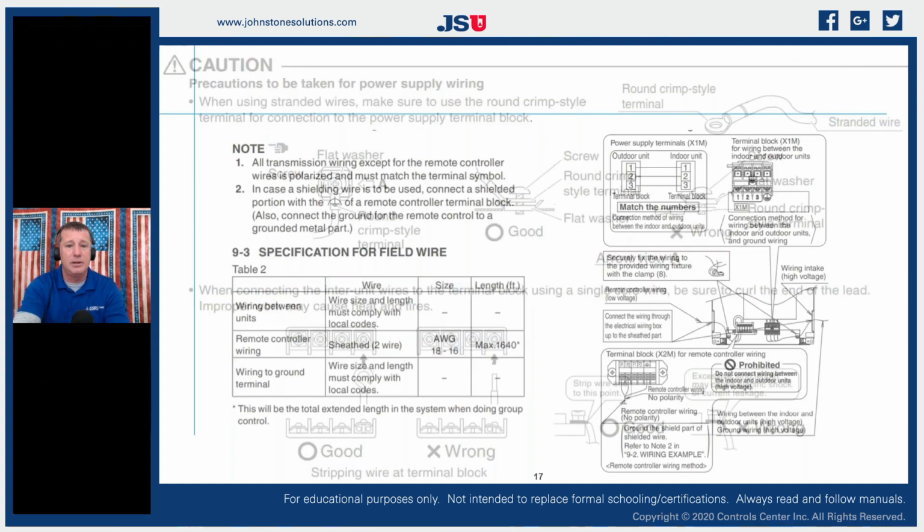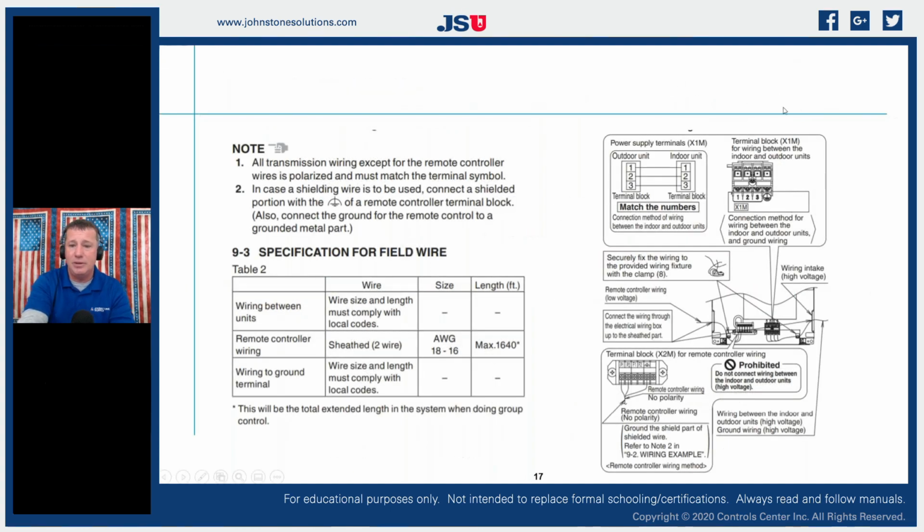So if we look at another slide out of these installation manuals, you're going to see that this particular unit can be used with solid and stranded, but in some applications it requires stranded even for communication. So we have to make sure we know what wire is being called out. In these manuals for our pieces of equipment, we have to pay attention to what is allowed and what is not.